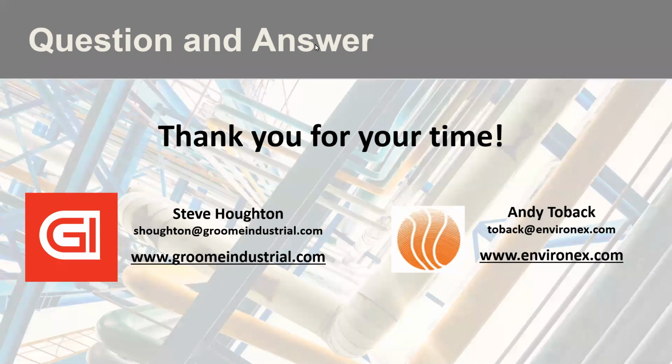Would sampling for ammonia slip at the HRSG exhaust stack be a good indication that an AIG tuning is needed, or would the ammonia plating out on the tubes throw off the results?